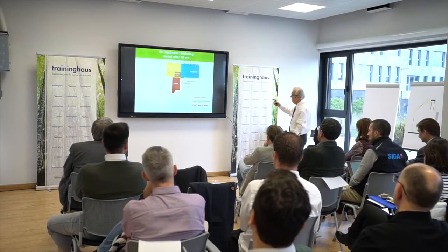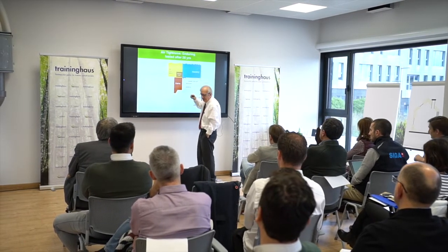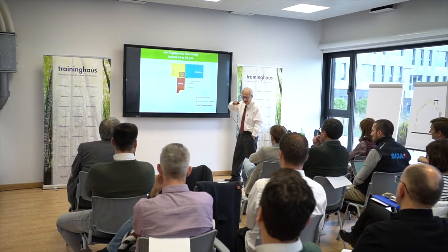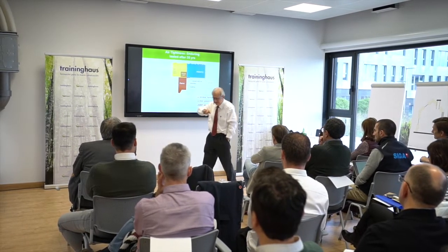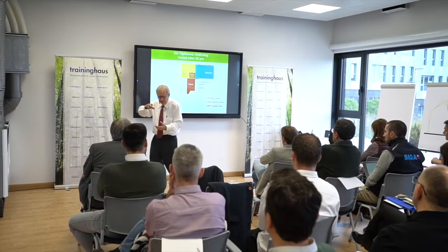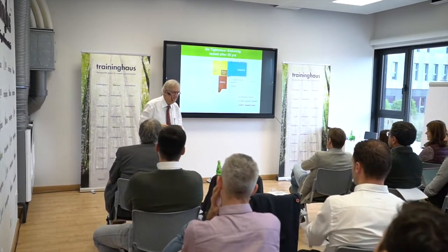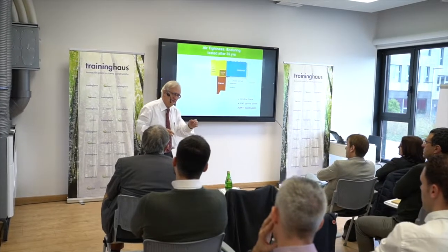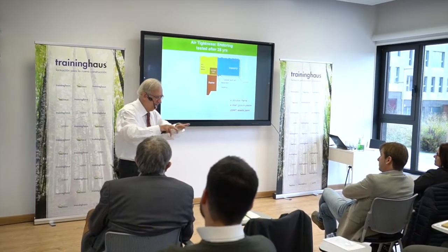That is how to have an airtight connection in a masonry construction to a window. Now there is often a misconception here, that you try to connect the masonry wall to the window. This is how people think about it. Now we have to see that a masonry wall is not airtight. The masonry itself is not airtight.